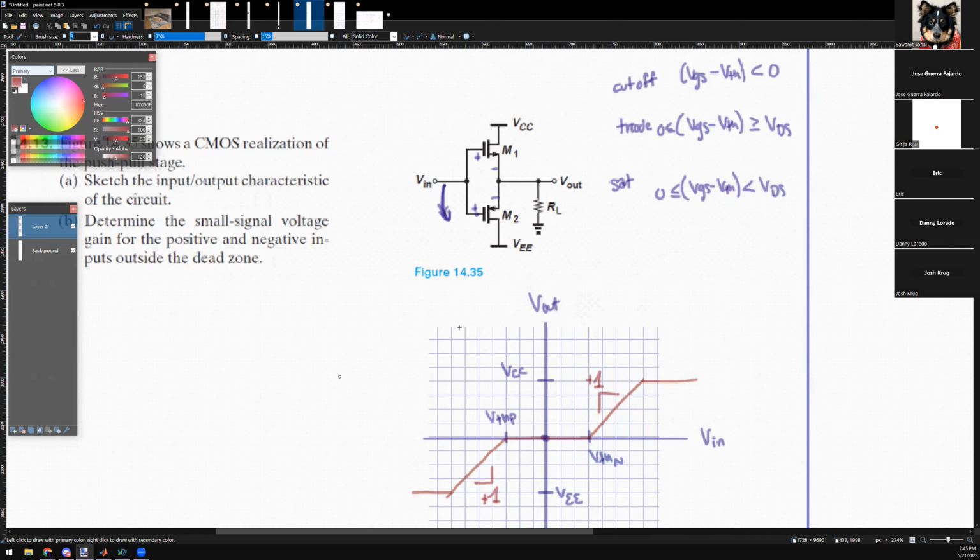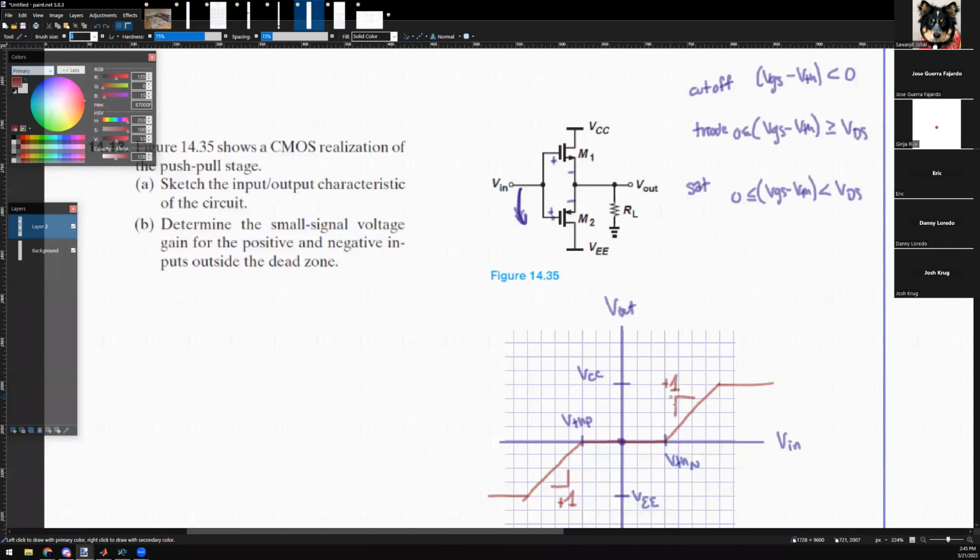So then you might ask, what's the point of a source follower if it has no voltage gain? Don't look at the voltage. Remember, in electrical engineering, we have two things. Look at how much input current flows into this guy. None. You agree? I in is 0. Look at how much I out goes. It's a huge amount because you're channeling everything through these guys. So I out is huge. A source follower has no voltage gain, but it has massive current gain.